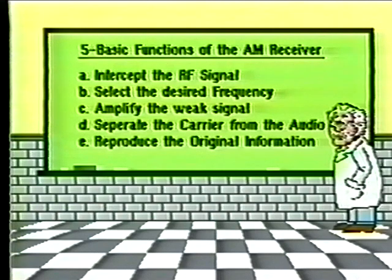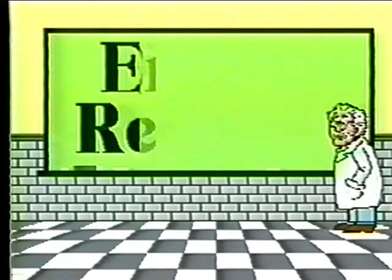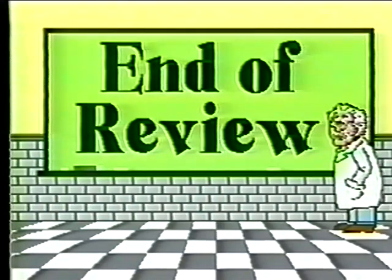And you learned that a radio receiver must perform 5 basic functions. It must be capable of intercepting the radio frequency carrier wave, selecting the desired frequency, amplifying the weak signal, separating the carrier wave from the transmitted information, and it must be capable of reproducing the audio information back into a usable form. Now that you have a better understanding of the function of each of the blocks contained in the superheterodyne receiver, let's continue with the video and learn more about each of these stages. We will begin with the RF amplifier stage.